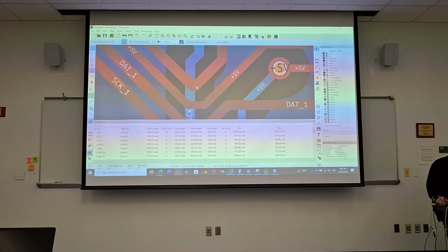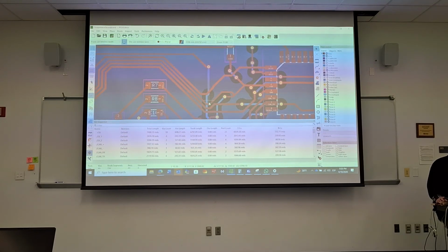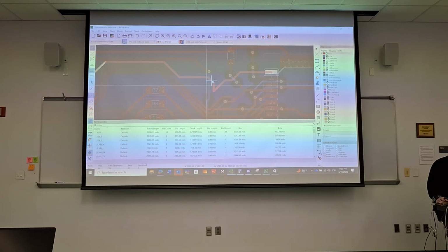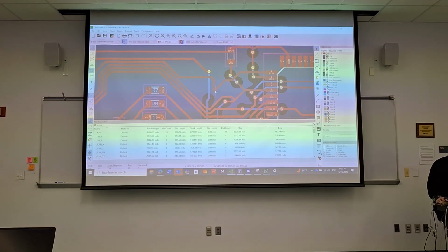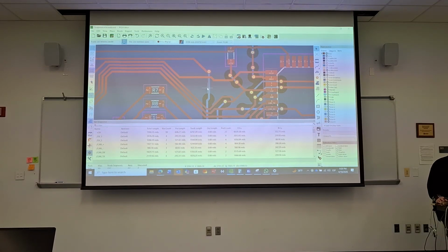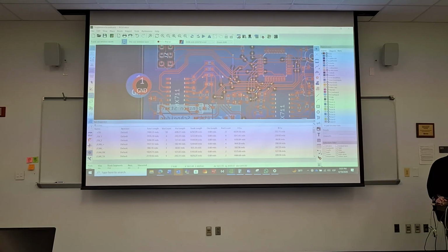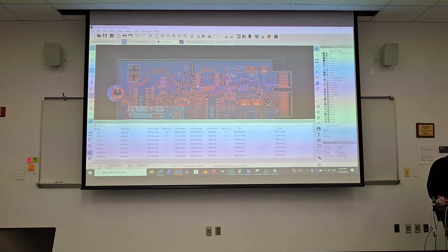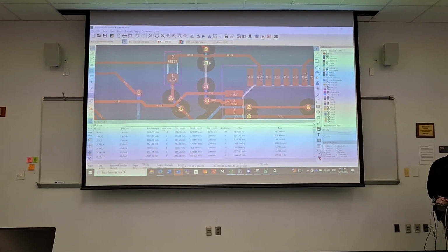I need to work on the key bindings on this thing, but right. And so this is nice and straighter, and all of a sudden there would be a void there. But what we can do is just avoid that void. And if we assume that this trace were straight, you know, that's a lot better, I would say. And then you could fix all of these other ones. I would look to see if we can reduce the amount of vias going on. As I mentioned, just making this a straight shot.